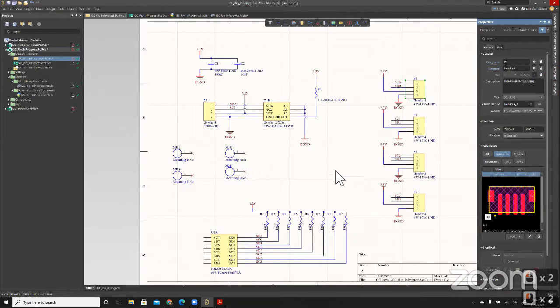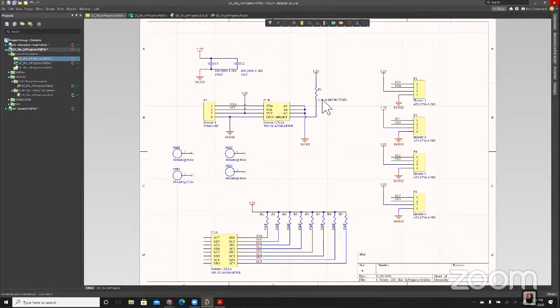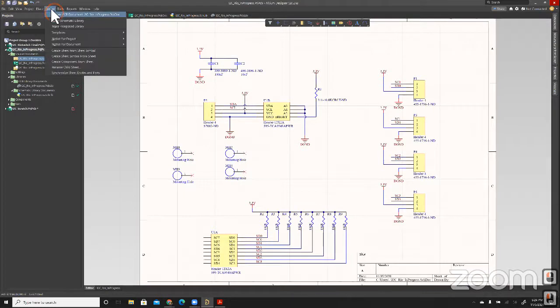You can see that that's the JST footprint. When you use the integrated library, sometimes you'll have to go and manually control some of that stuff and make sure that it doesn't use the wrong one. I use the integrated footprints for the capacitors and resistors that I've added because I didn't want to do more.